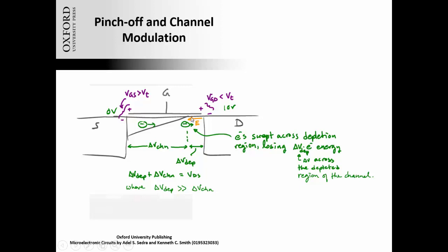Those electrons, once they get near this electric field here, will get just swept, accelerated across this gap, right? But as they move across that gap, they are also losing energy, because as electrons, they're moving from a more negative potential now to a positive potential that is 9 volts more positive. Right, so that's analogous to positive charges dropping through a potential difference.